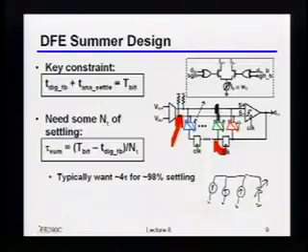But I'm still talking about just, let's say that I try and build this thing, and I look at all of my channels, and I figure out that over all of my channels, just the worst case on each one of them, when I add those all together, is just too large. It's just too much capacitance for me to close the loop at that speed. What can I do? Like the shuffling stuff? Similar. Cascode? Okay, that actually also turns out to work, but for a different reason.